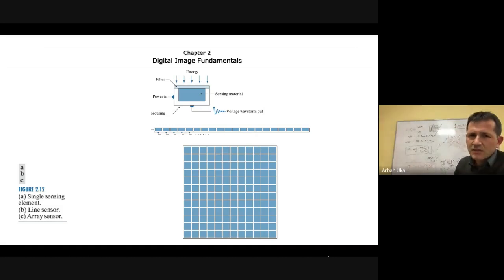What we are discussing for this slide is not something fundamentally essential for computer engineering students, but it is fundamentally essential for electronics engineering students, because they have taken all the necessary courses to understand that once a photon falls onto a specific material, it is going to excite some electrons, and these electrons fall into a photomultiplier tube, and this photomultiplier tube produces 1000 electrons for each incident electron. So the incident signal is going to be multiplied by at least 1000 times.